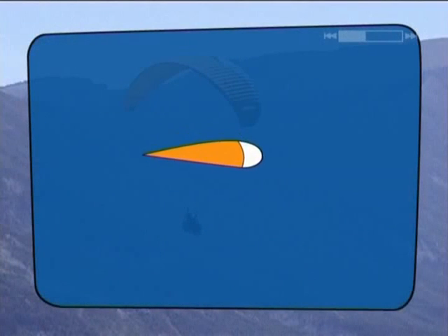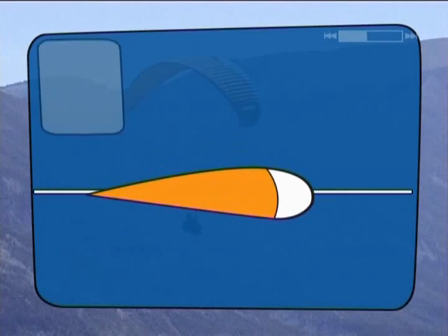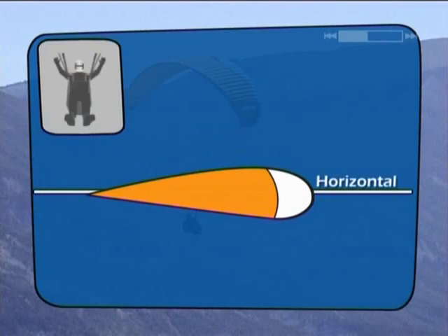Paragliders have a large speed range, and knowing when to use these different speeds is very important. You have control of the speed with the brakes and the speed bar. This is known as speed to fly. Knowing to fly at the right speed, depending on conditions or the site, is the basis of safe and efficient piloting. Understanding different flying speeds will make you a better pilot.